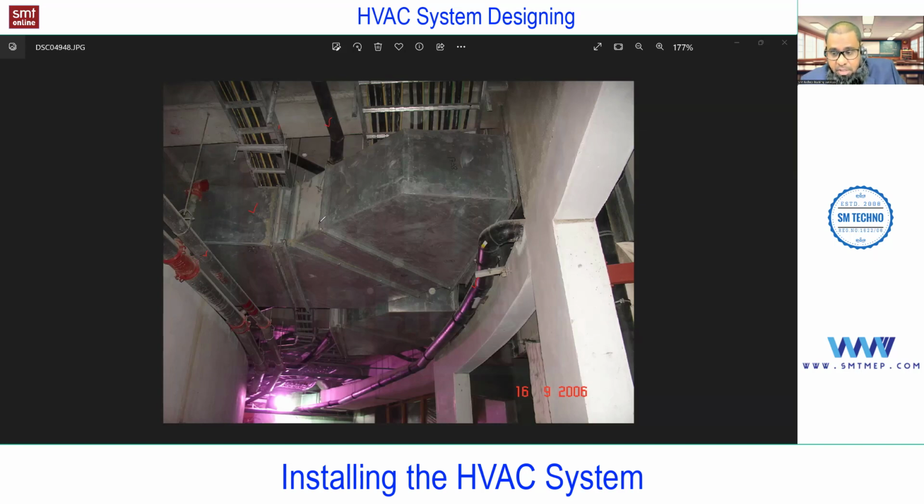So remember the height of the duct. If I use the term height, it is related to rectangular including square. There is no question of height for round and oval. For that, we have a diameter. So forget about round and oval. For rectangular or square, the height of the duct will be decided as per the clearance available, considering the clearance required by other services. This is one difference. But again, this is not that easy, that one can take a quick decision. You need some experience, based on which you can judge, because again, in the height of the duct also we have some limitation.